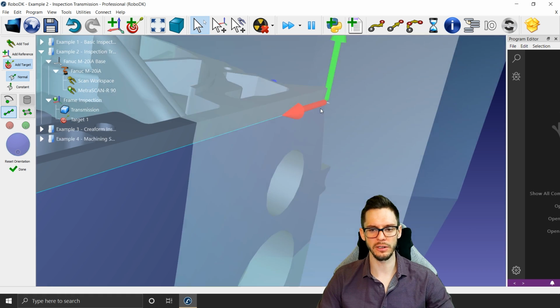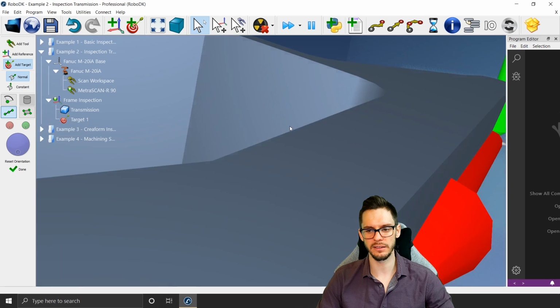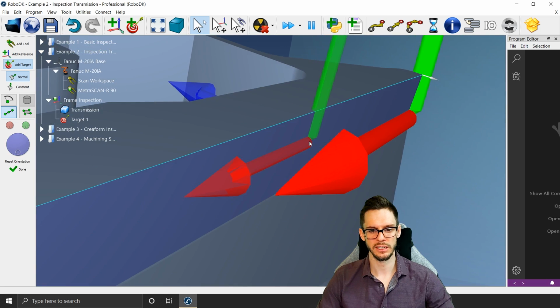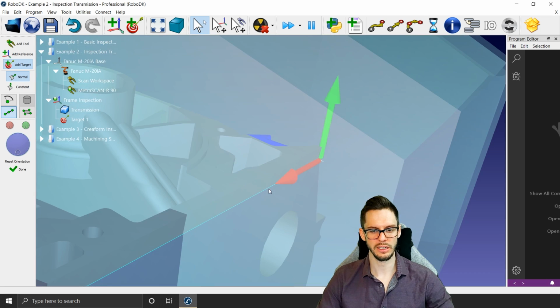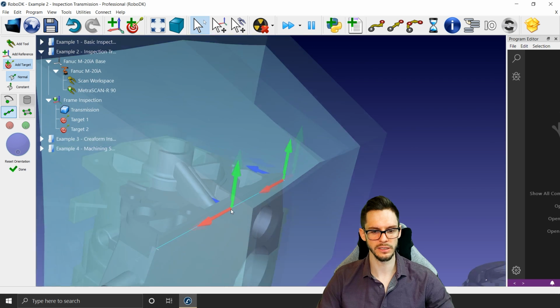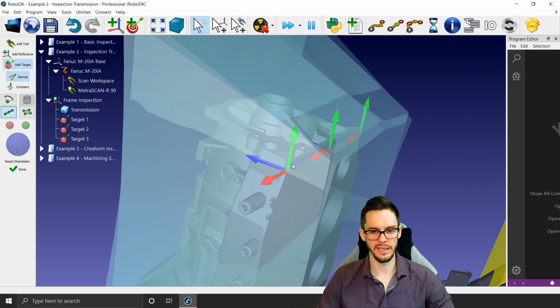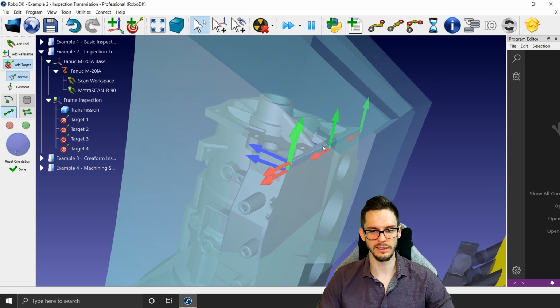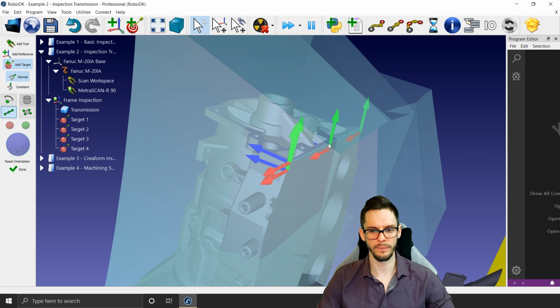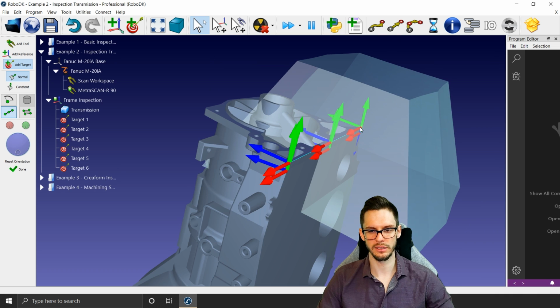And if you're close enough and you press, it will create a target right at the end of this surface. Same here for the middle point of this line, and here with the end. Let's create the end here, the middle point like that, and the end point just like that.